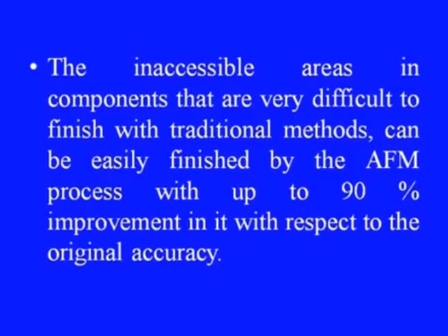The inaccessible areas in components that are very difficult to finish with traditional methods, as I have already explained, can be very easily finished by the AFM process with up to 90% improvement in the surface with respect to its original accuracy.